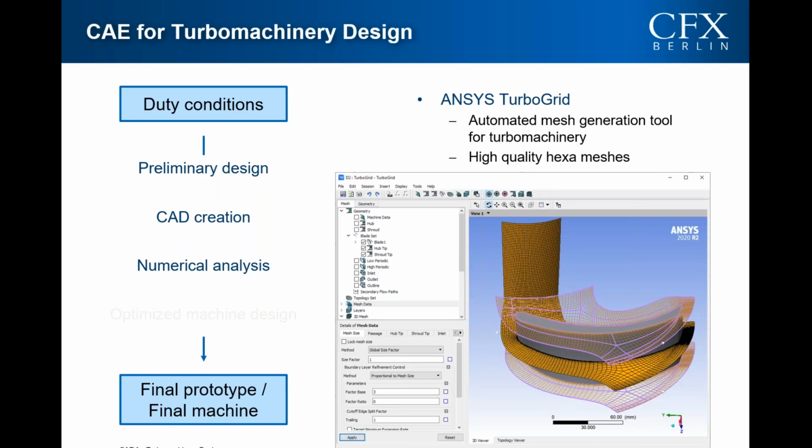So computational fluid dynamics software works with finite volumes. So of course, before we can analyze the flow, we have to create a computational mesh. The workflow here makes it very easy for us to do this. And this TurboGrid automatically creates high quality meshes for impeller geometries. Basically, we only have to adjust the element sizes if needed. This approach is also very robust to geometry changes.